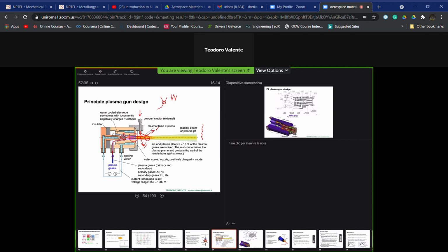But nevertheless, local melting can happen due to the localized electrical discharge. And so this means that these cathodes do not have an infinite life. They must be changed after a certain period of time that depends on the spraying process which is going to be performed. They are treated essentially as spare parts.